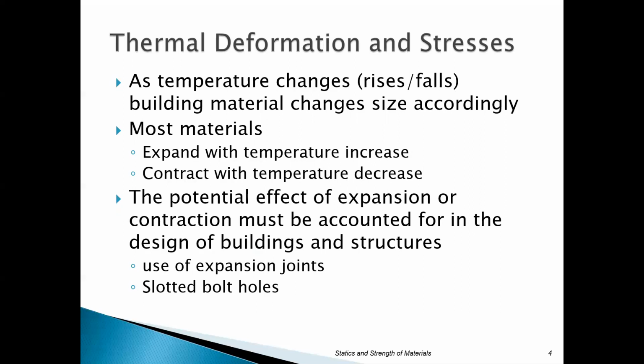If you don't allow movement, you're going to get stresses developing, and you can actually fail pieces. I've actually seen on hot summer days, if they don't have enough expansion joints in concrete, that concrete will come together and actually more or less explode.